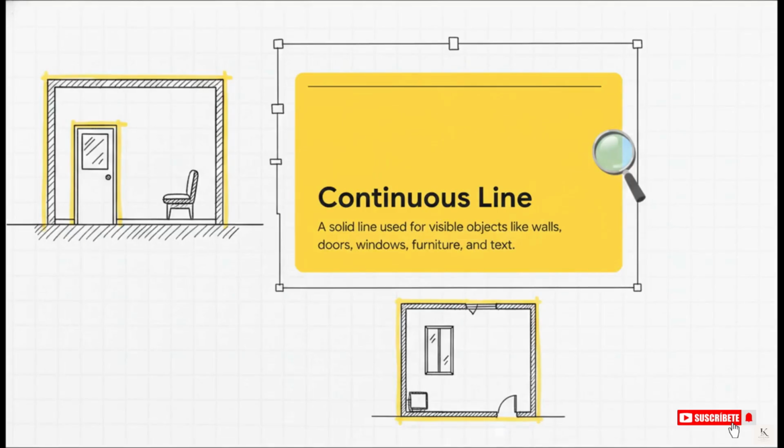Now, you might have noticed a trend in the line types we've discussed so far. They are all continuous lines. A continuous line is simply a solid line used for visible objects, things like walls, doors, windows, and furniture. It reinforces a really simple rule. If you can physically see the object when comparing the blueprint with realistic images of the space, it gets a solid, continuous line.